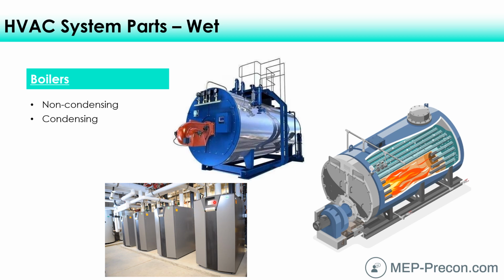And these are what condensing boilers would look like. The way that you can tell them apart if you saw them in the field is that usually a non-condensing boiler would have a metallic flue, but sometimes condensing boilers could have a metallic flue too. These would be usually stainless steel, perhaps a shiny stainless steel exterior, but they could be PVC as well, or polypropylene, which is a real effective, inexpensive flue for condensing boilers. It just depends on the manufacturer, really, whatever their recommendations are for the size of the boiler and the temperature of the flue gas too.